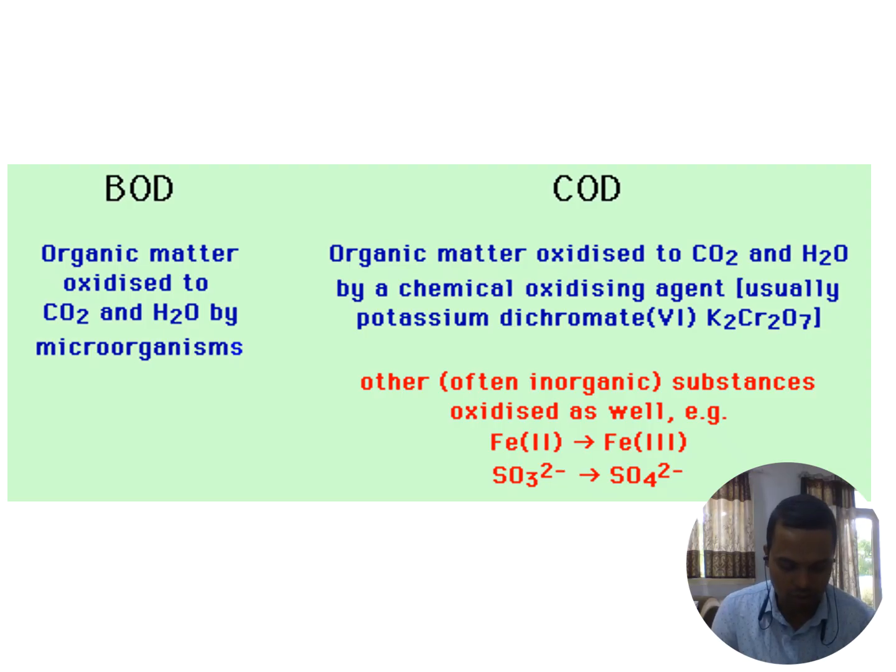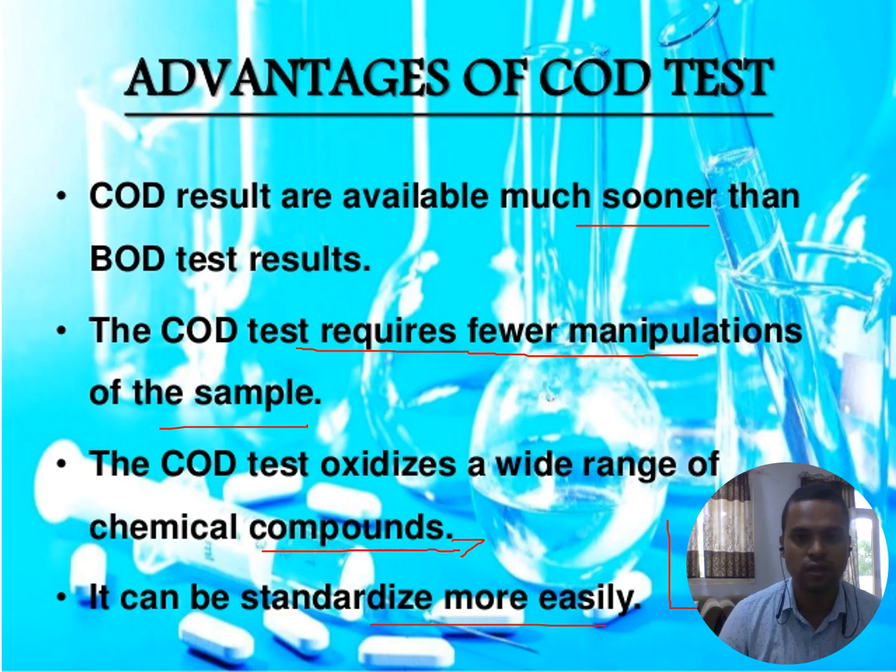It is a very standard procedure, but at the same time it requires time and patience to get the amount of dissolved oxygen present, which is needed for biologically degrading the organic materials, the waste materials that can be biologically degraded. If you compare BOD and COD, BOD is organic matter oxidized to CO2 and water by microorganisms. COD is organic matter oxidized to CO2 and water by chemical oxidation. So those are two different things.